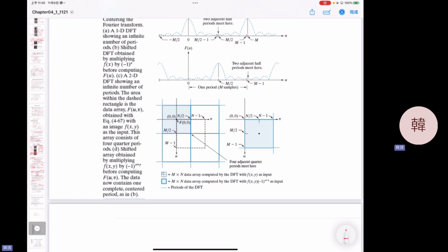So in the center and shifting, you can see when you shift the image to a different location, the phase spectrum is totally different from the previous one. Although they have identical image content, but you are shifting. When you shift, the result will be totally different in phase spectrum. And the magnitude spectrum is exactly the same, right? The top one and that one are exactly the same. They have the same magnitude spectrum, but the phase is totally different.